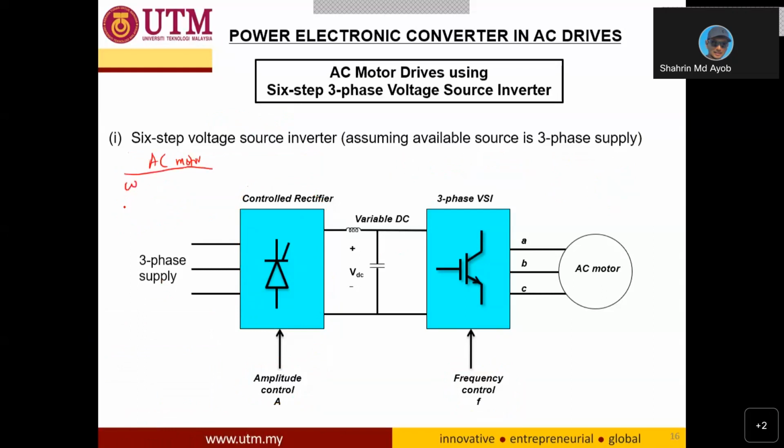Okay, AC motor, speed and torque, how to control? The speed, as said earlier, is the frequency of the supply. Torque is a bit harder. Torque is V over X. Right? Not direct V. So V supply over X.